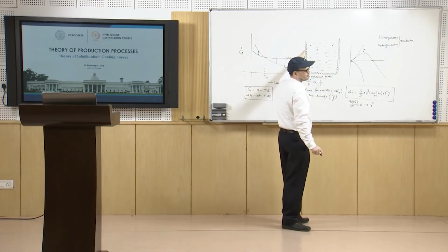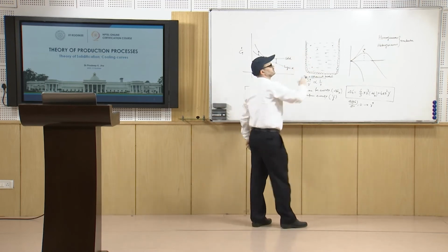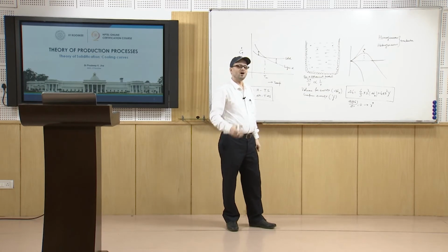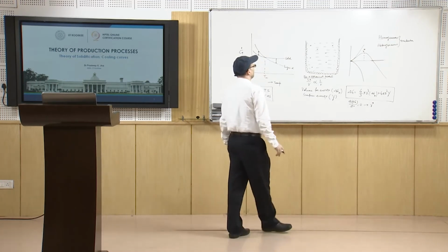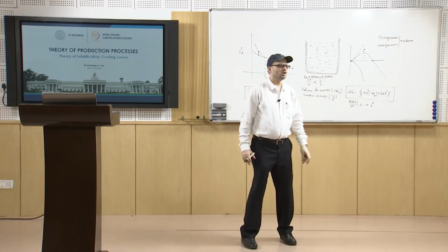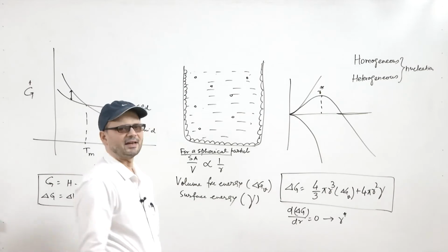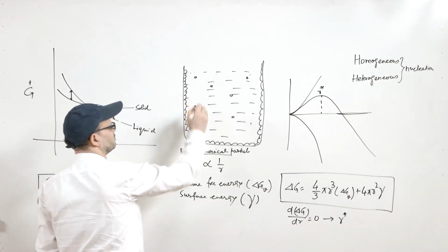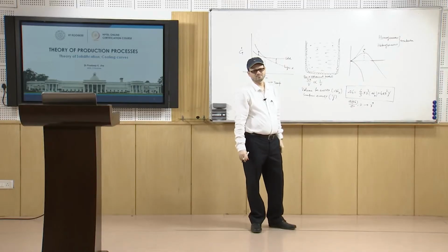If the surface is rough here, most likely the first nucleation will start at the surfaces. Now, in the case of solidification, as you know, it will be losing latent heat. That heat lost will go through this side, and it will also go from this direction. So heat goes in both directions.